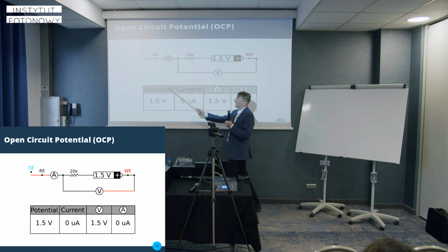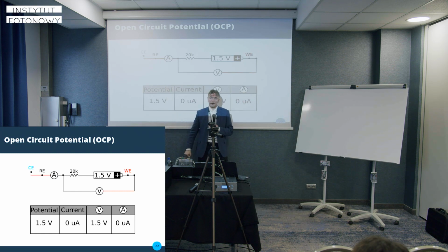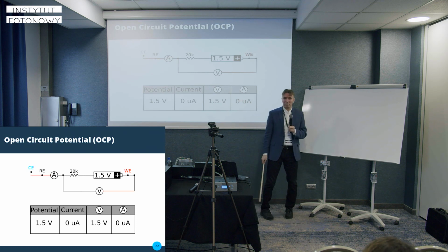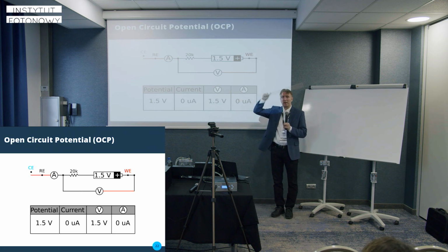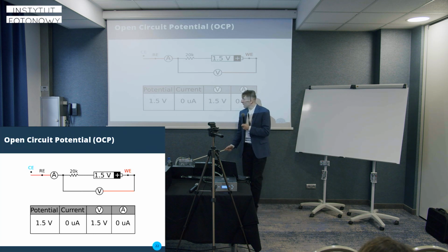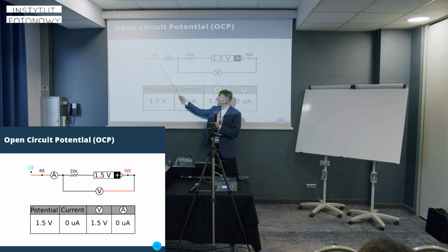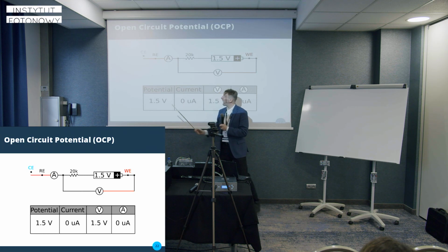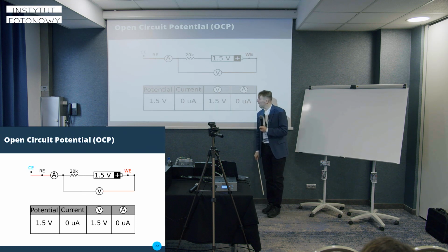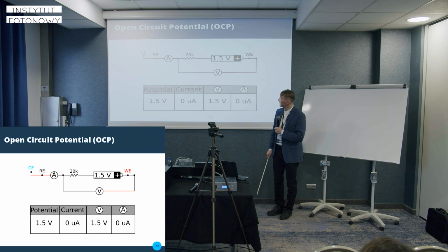So now we disconnect this C electrode from the circuit. So the circuit is open. It is no longer being shorted by the ampere meter. It is open. And we actually use our internal potentiostat, internal voltage meter, as a meter, and it will be measuring voltages between RE and WE. Okay.